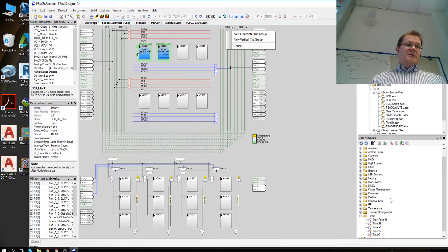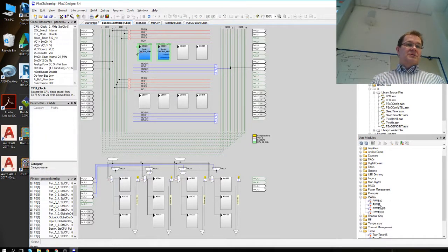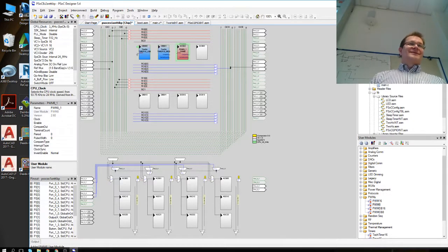Anyways, everything starts from this designer again. Add here the PWM. I will add 8-bit there, but I think this is not enough. You don't get enough resolution, but that's the reason why I'm using this as an example. The clock. Okay, now which clock to use? Plenty of different sources.